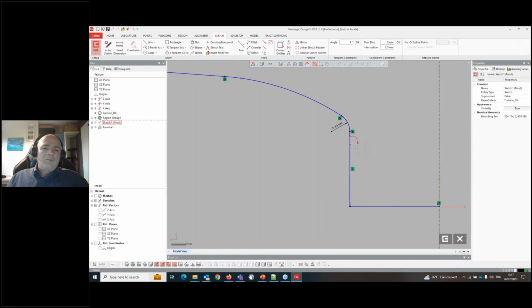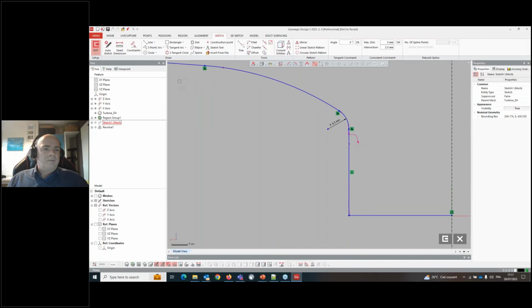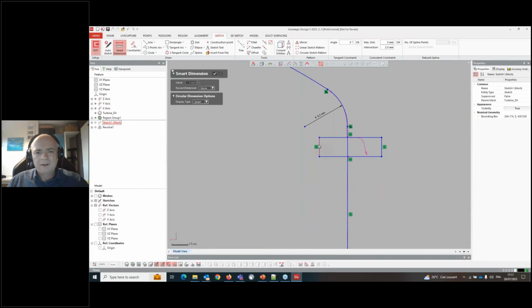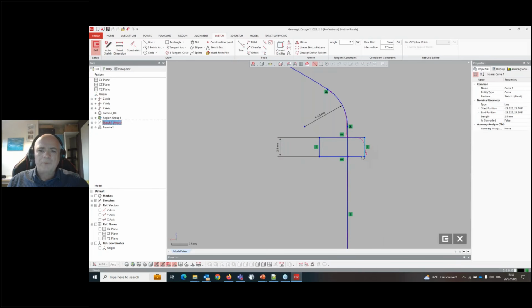Right, I just missed this groove, which is not really well scanned. So I will just put a groove here, magnet the groove on top, magnet on the bottom. You can see the size here, get some dimensions on that groove. So here, I will just round the value to 10th of millimeter and put the start of the groove right here.